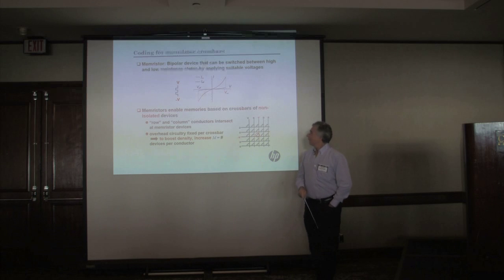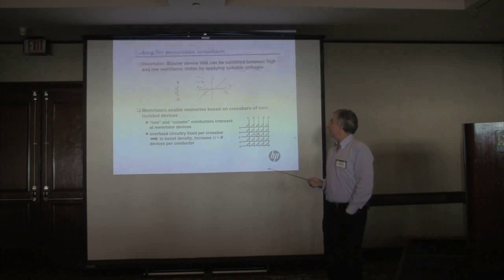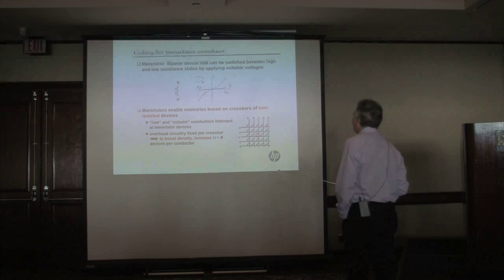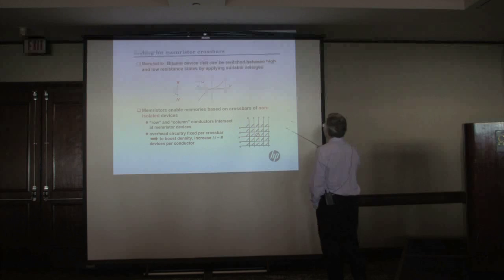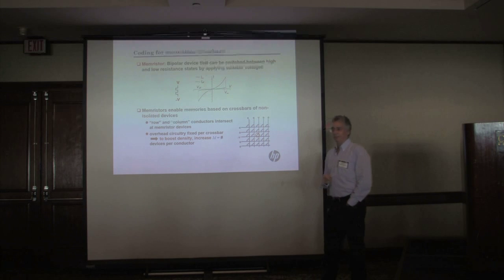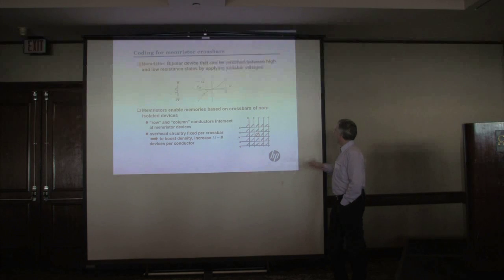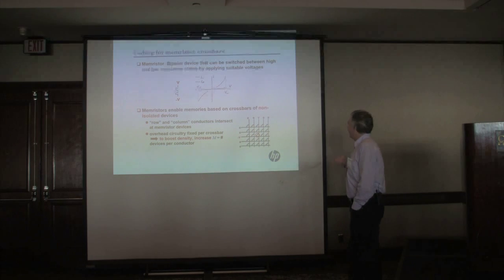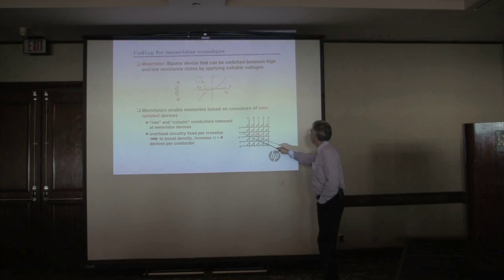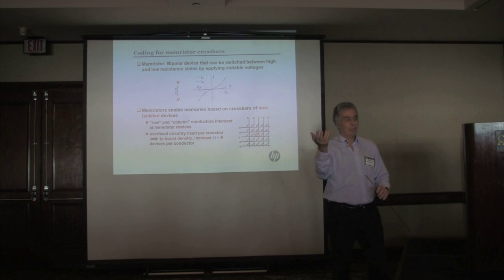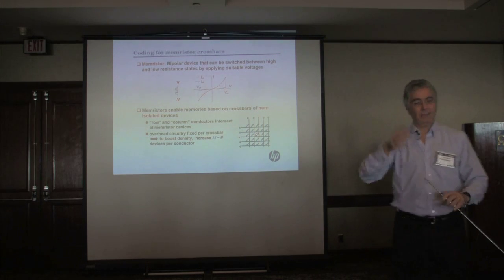And based on memristors, HP and probably other companies are trying to build memories based on crossbars of non-isolated devices. So what you have is a crossbar. You have nanoconductors here and here. At each intersection you put a memristor, and you apply a voltage. If you apply one voltage or the opposite, you switch the memristor from the on state to the off state, and conversely.